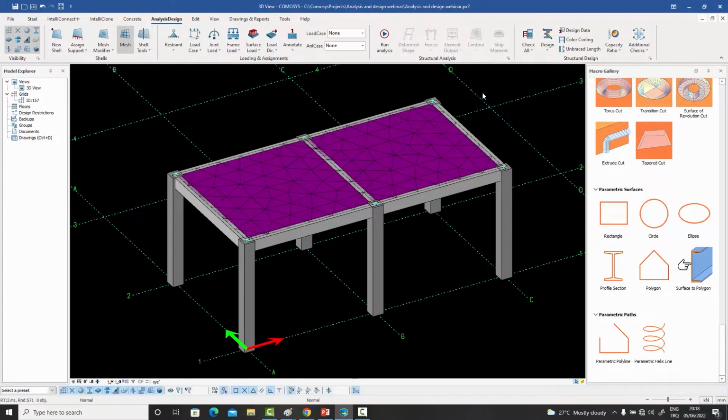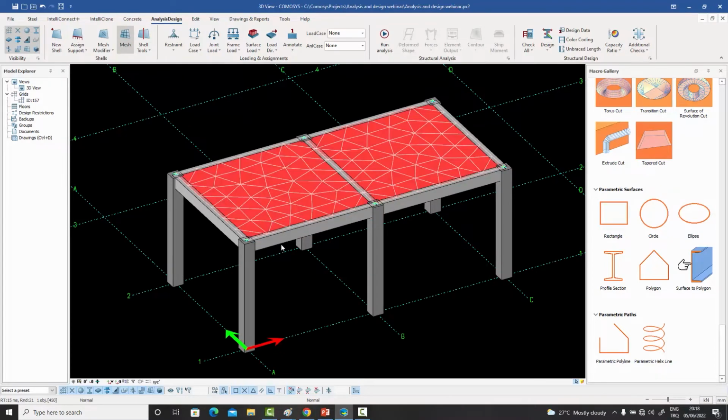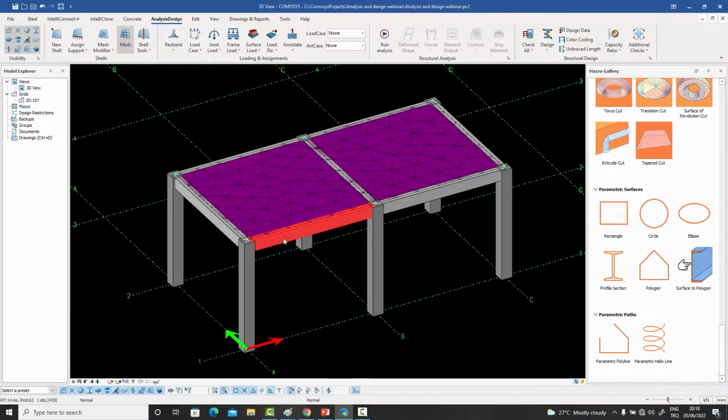One thing I want to say at this point is that these beams you see over here, because the supershell will be meshed like this, at these points, for the finite element stiffness matrix assembly, this beam will also be broken into little parts in the background. You won't notice that, but in the background, while it's assembling the stiffness matrix, in order to have continuity in the displacements, these beams, wherever they're touching the supershells, will be broken down into their own subparts.